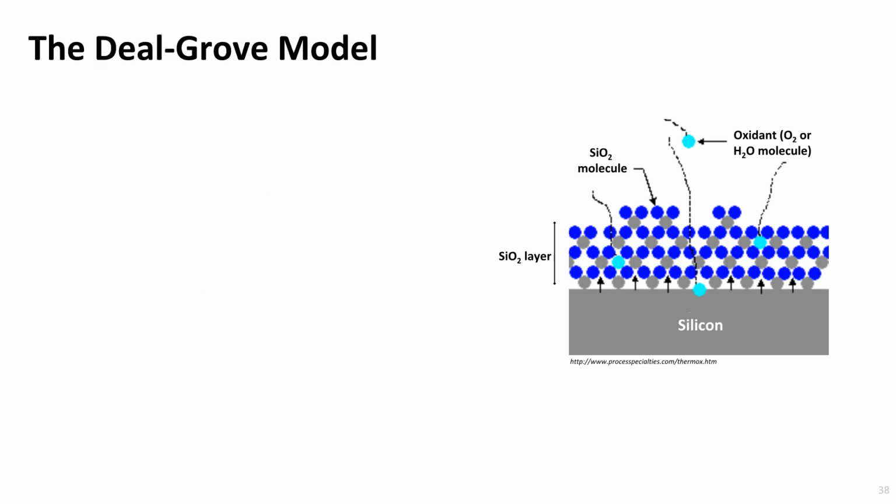The growth of thermal silicon oxide can be predicted using a mathematical model, called the Deal-Grove model. It was invented by Bruce Deal and Andrew Grove of Fairchild Semiconductor, published in 1965. It laid the foundation for understanding and predicting thermal oxidation of silicon, fundamental for semiconductor manufacturing.